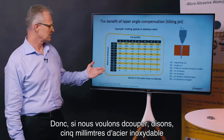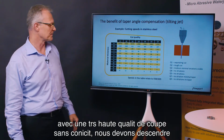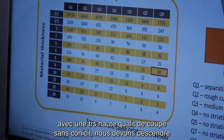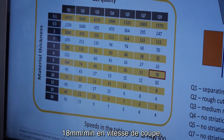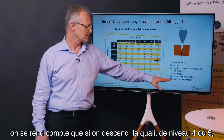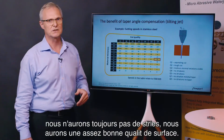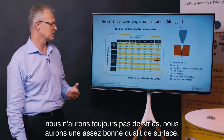So if we want to cut, say, 5mm stainless steel at a very high quality cut with no taper, we will need to go down to 18mm per minute in cutting speed. But if we look at the surfaces we produce, we can see that if we go down to quality number 5 or 4, we will still have no striation. We will have a quite good surface quality.